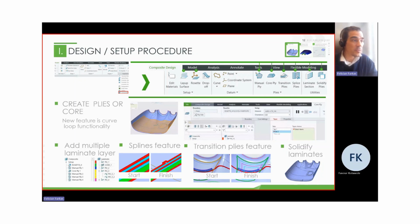We have the option to split the plies up, use the splice features, and we can overlap this. You can see the start and the finish as it overlaps the top layer in red. We control the layers and transition them with the transition plies feature, stacking them in steps, as you see on the transition plies feature image.